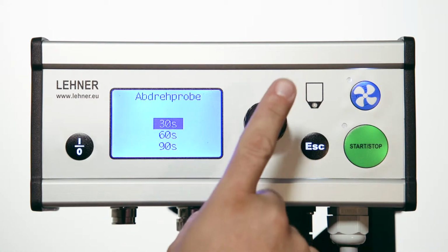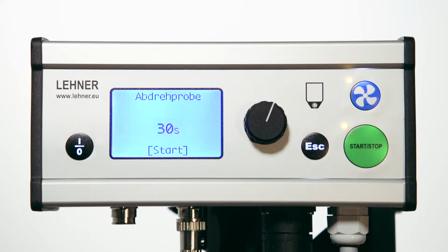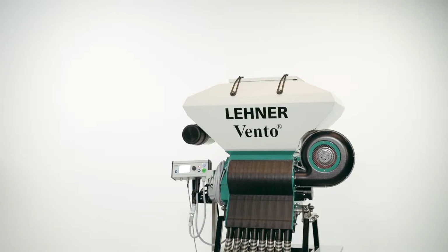Once you have done this, select the time duration for the calibration test. Calibrating homogeneous material usually would be set to 30 seconds. Select a greater time for coarse or mixed material or for a more precise calibration test.